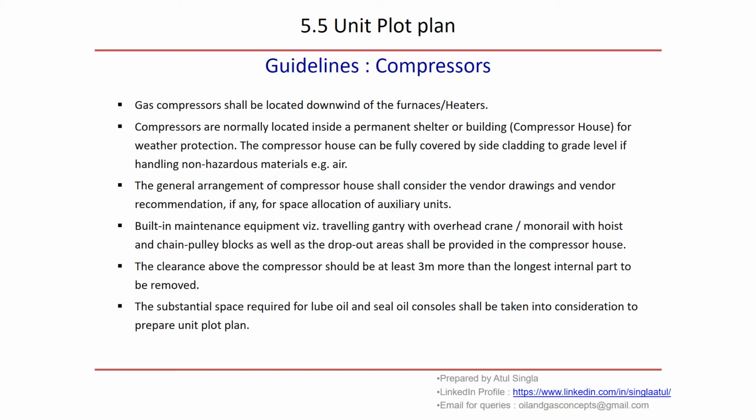At that time we require some vendor recommendation also, because there are many auxiliary units with the compressor, such as lube oil and water consoles. We prepare a layout and share it with the vendor. If they have any comments, they provide them. If they are okay with the space allocated, they say okay, go ahead.